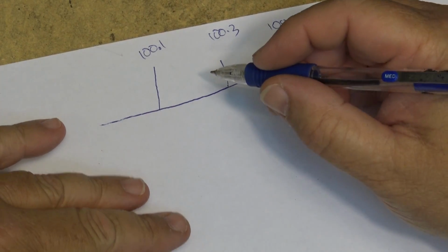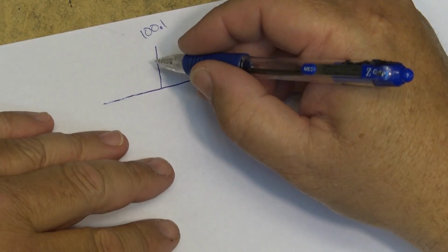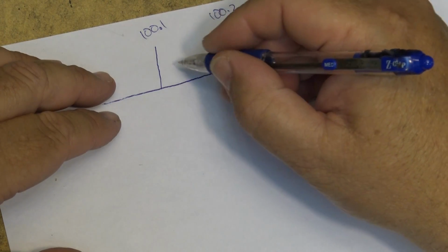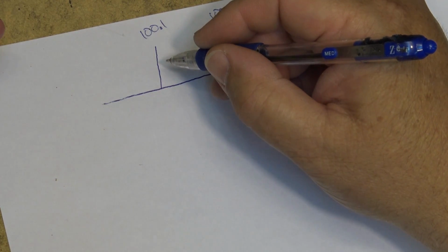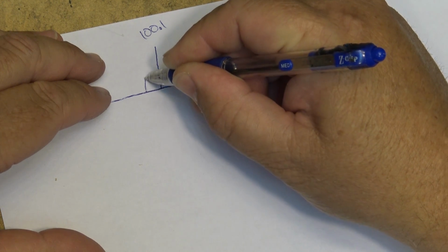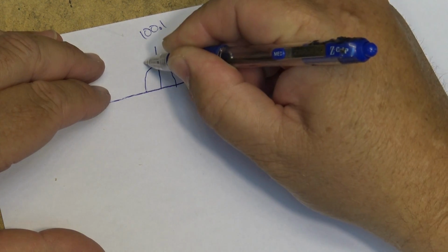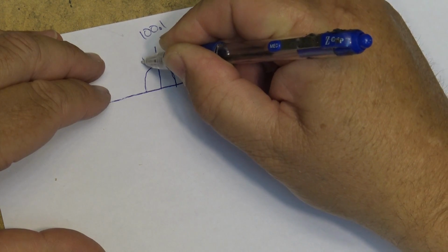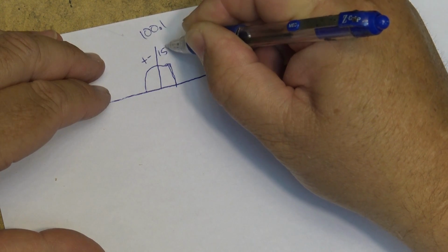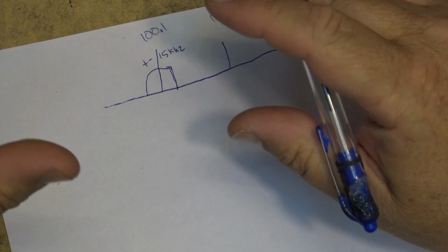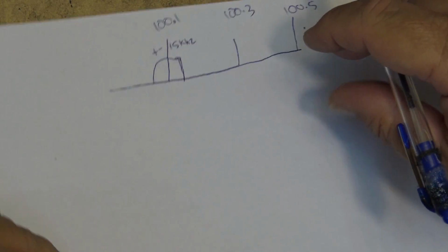Now, your audio spectrum only uses about 20 kilohertz either side, give or take. Actually, your FM is limited to about 15. But here's our audio spectrum. Our audio spectrum goes like that, approximately, plus and minus 15 kilohertz. This is the audio bandwidth I'm referring to, not the deviation. I'm going to draw this a little bit bigger, but this is to give you an idea.